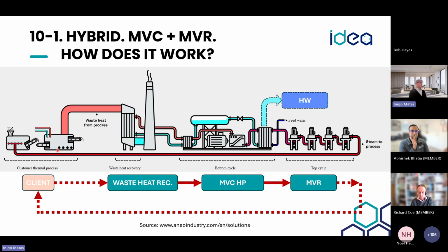In this example that I'm showing on the screen, this will be a dryer, and we will have these vapors, a humid air, so it's giving good energy, and we can capture that in this loop, which can be a water loop. Then this will be the heat source for an ammonia heat pump, another type of refrigerant, as we were explaining before. It's going to give us water at 85, 90 degrees.